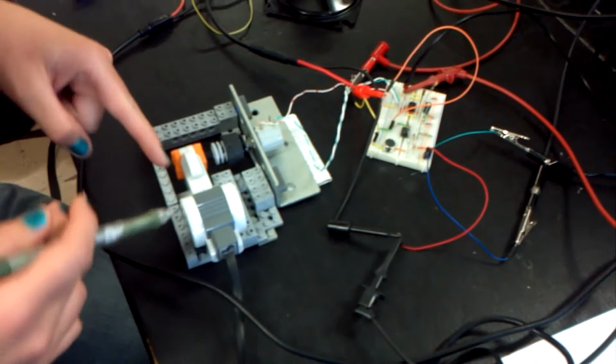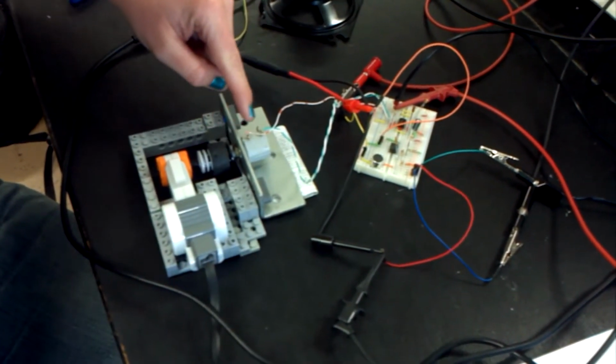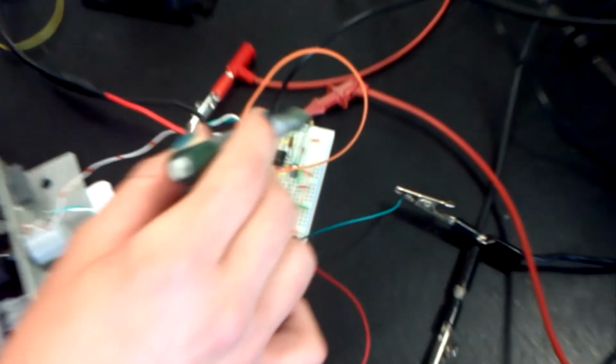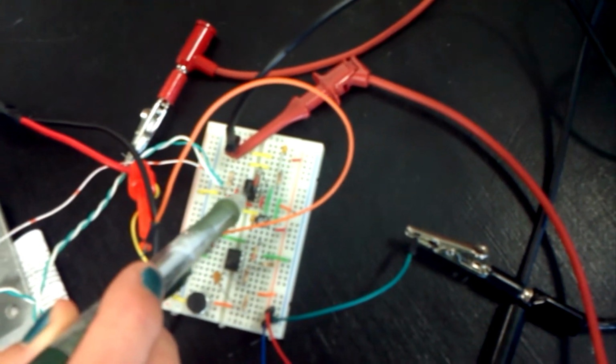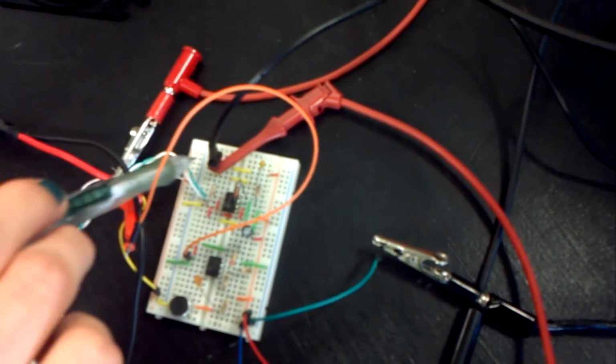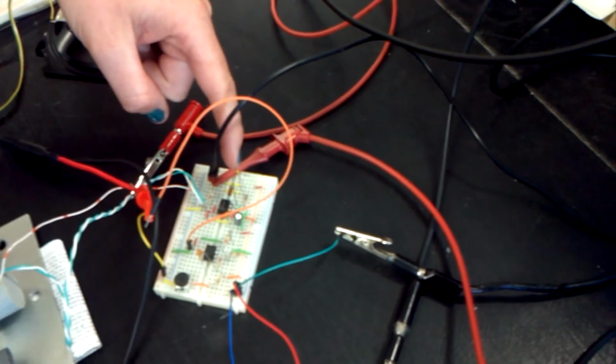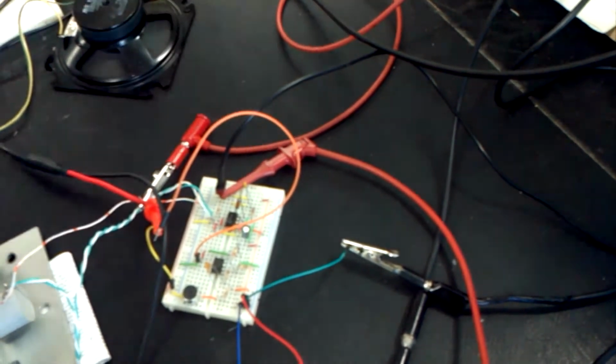From the LabView code, that goes to the NXT, which powers our motor. This motor in this fancy setup turns this potentiometer, which in turn changes the frequency of an oscillating circuit governed by a 555 timer. So that frequency finally goes to these lovely speakers here to make an incredibly pleasant tone, which we tried to make even more pleasant with use of this capacitor to filter out some of the awful high-pitched harmonics that happen.